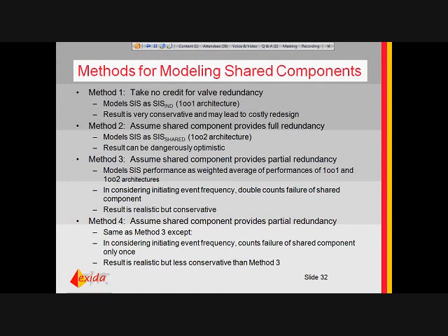In this example, we're using 2 valves, only has this safety shutoff valve, and for all other initiating events, assume that you have redundancy. And method 4 is the same as method 3, except in the standard it says to model basically 0.1 probability of failure of 0.1 per year for the basic control system to be initiating event. And then method 4, we do the same thing we do in method 3, but we pull out the failure rates of the actual valve assembly from the 0.1%.